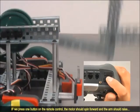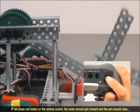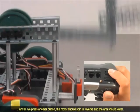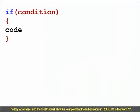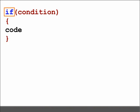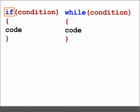If we press one button on the remote control, the motor should spin forward and the arm should raise. And if we press another button, the motor should spin in reverse and the arm should lower. The key word here, and the tool that will allow us to implement these behaviors in Robot C, is the word if.